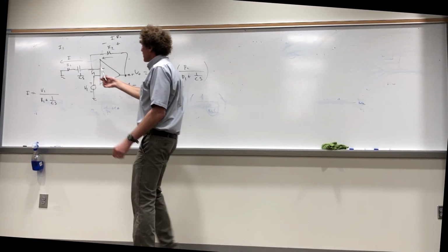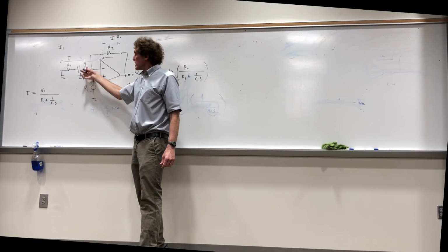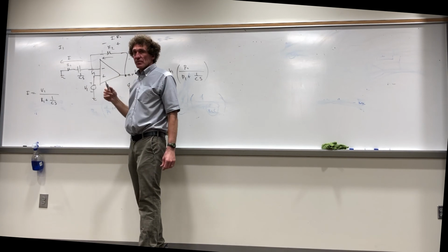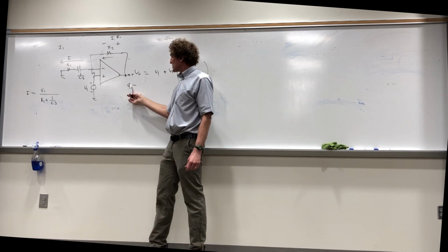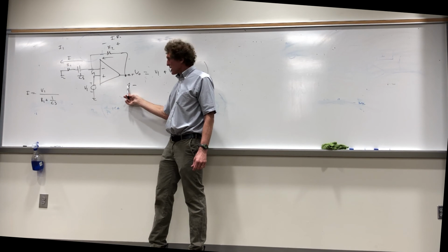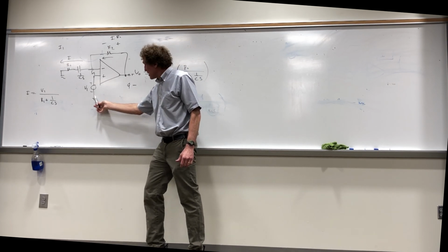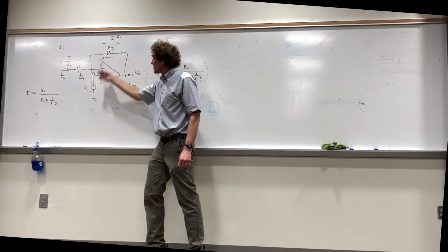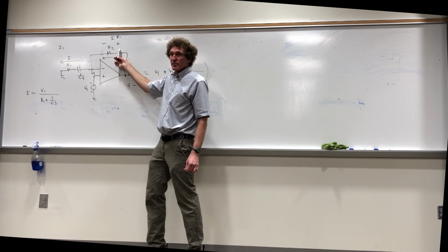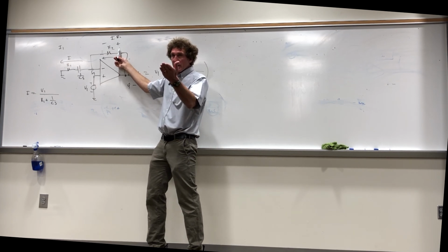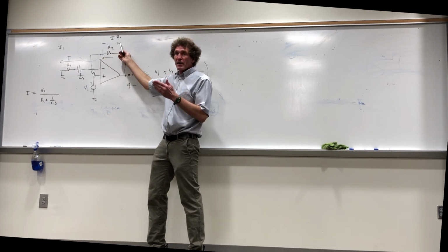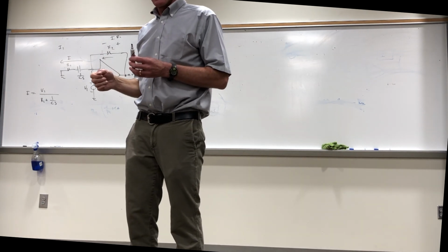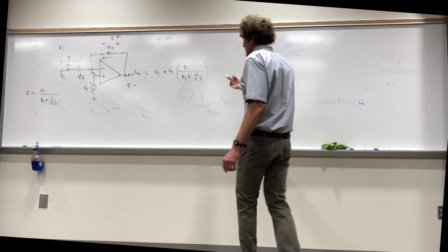First, you see how I got this current, I. You all agree that I flows this way. You all agree this voltage is that I times R2. If I want the voltage from here to here, I start at the negative terminal, right? From ground to that point is V1, isn't it? Plus, what's the voltage from here to here? That's an increase, isn't it, of I times R2? You went from lower to higher. And isn't I just V1 over R1 plus 1 over CS? Right? So isn't this it?